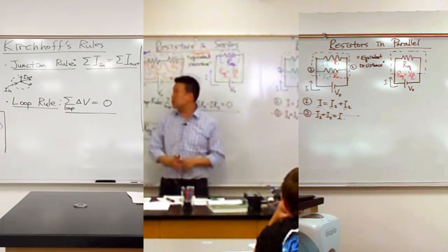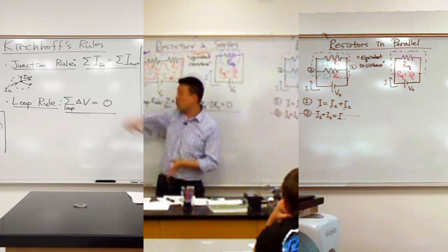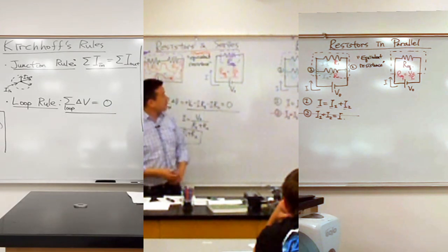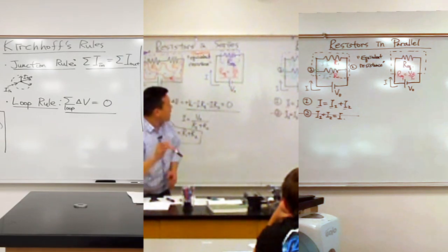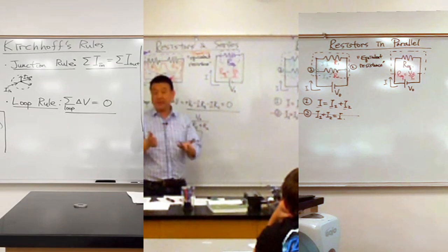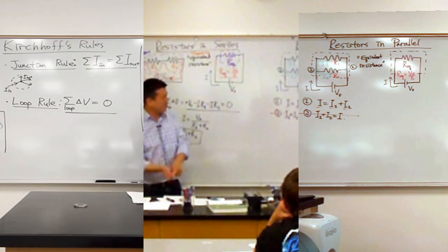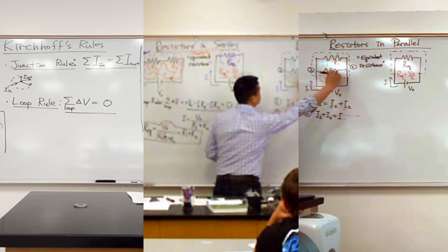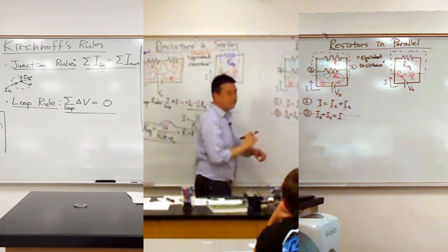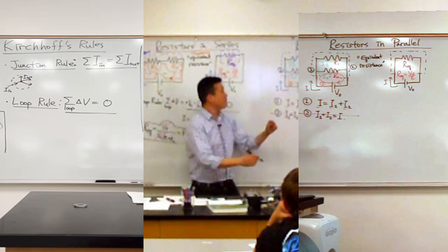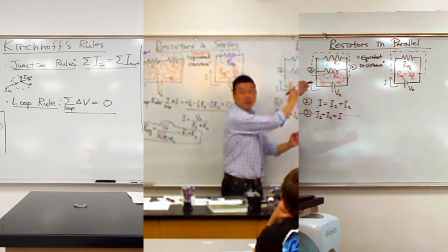So now once I have used the junction rule, I have the benefit of knowing, okay, I need to use the loop rule exactly this number of times. So I'm going to try to find the 2 loops here. And let me do 2. So the general advice I would give is pick the loops in a way they overlap with each other as little as possible. As in, you would not do this. So you wouldn't say, okay, I pick this loop, call that loop 1. And I'm sure no one here will say, okay, having picked this as my first loop, for my second loop, I'm going to pick the exact same loop. Like, would anyone here do that?